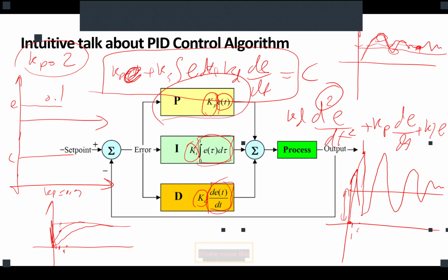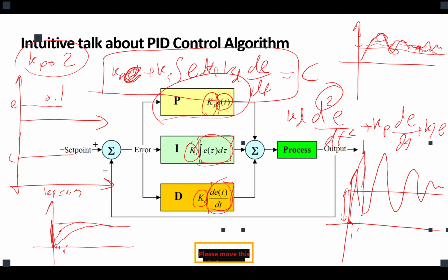So it needs more time to, 1% by 1%, eliminate that offset. Is that now clear? Yeah. So that Ki would also show you how fast you can, or how effectively you can, eliminate your residuals of the error, the accumulated error.